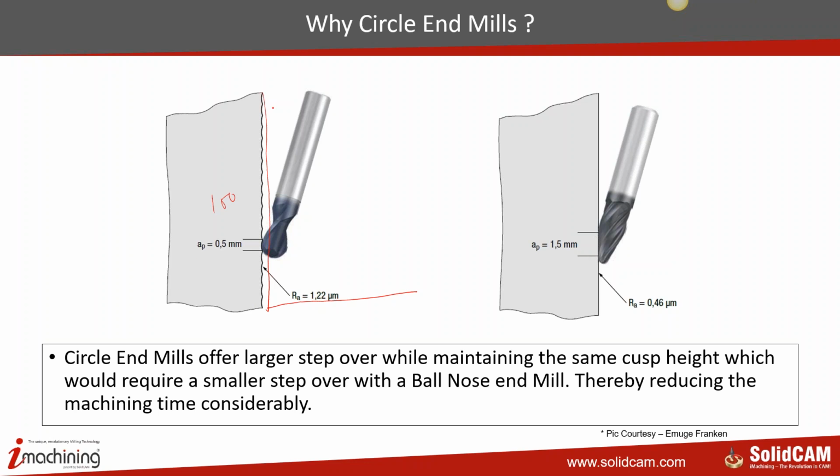It means that to machine this wall, I will have to use an end mill of at least 105 millimeter out of holder, and use the side of the tool to cut the part, like swarfing. But at 100 millimeter overhang, I'm not sure we are going to get a very good surface quality.